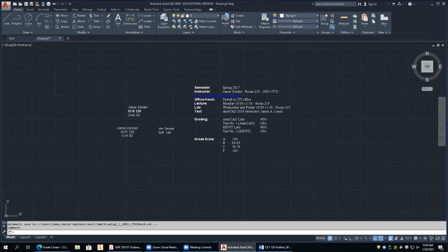Now, when you do these right here, this has got a point out here. It's kind of hard to see, but that's using a font called Roman V, and it's using a middle left, right? Middle left justification. So here's what I suggest you do. You offset this line half of the distance. This is a quarter, so that would be an 1/8.